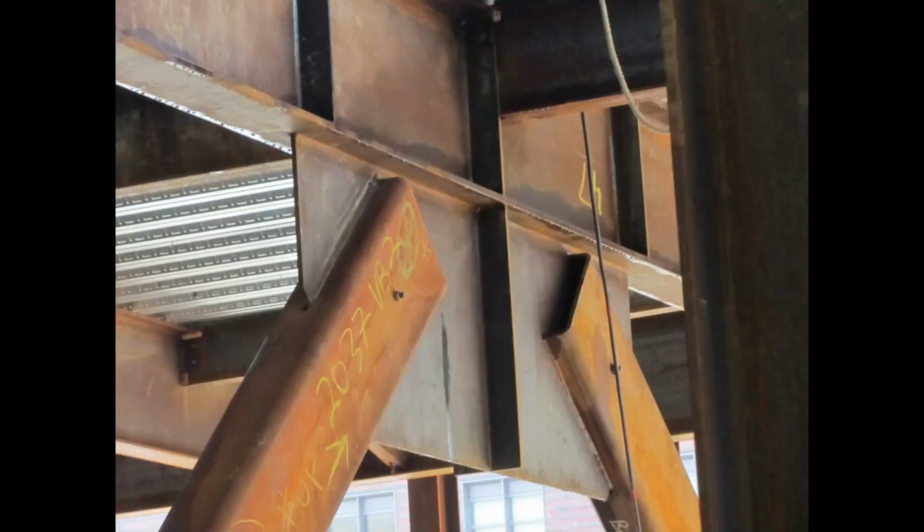These are interesting because welded HSS is often specified because architects love HSS sections. They're also quite effective, particularly if you have a brace that will be carrying either compression or tension depending on the direction of loading. HSS are often used as tension compression braces, and it's very difficult to bolt them in any other meaningful way. You can try to come up with a bolted connection, but 95% of the time, even if you're bolting it, you're still going to weld something to the HSS in a way that looks something like this.